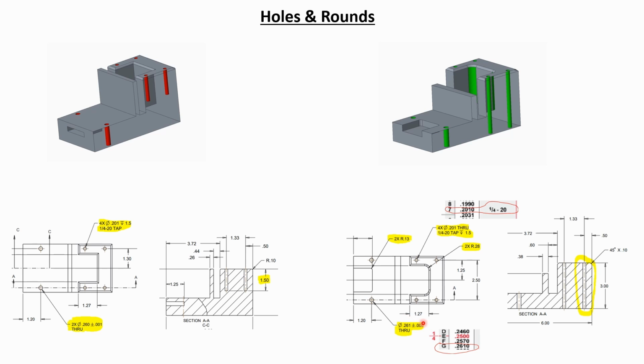While on the redesign, the 2.61 plus 5 minus 5 is attainable by using a readily available G-size standard drill. This information can be found within the machinist's handbook, and also the drill charts can be used. Remember, any extra operation adds up to the COGS and eats up your profit margin.